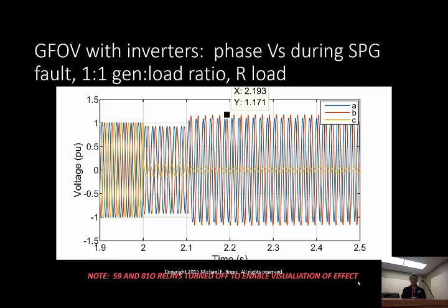But you'll notice what's happening here is that phase C voltage drops really, really low, and that power then gets rejected to phases A and B, which causes their voltages to rise just a little bit. So that's what's happening here. Notice that they're all still pretty well centered around zero, right? So this isn't that neutral shift issue we were talking about. We just don't see it.